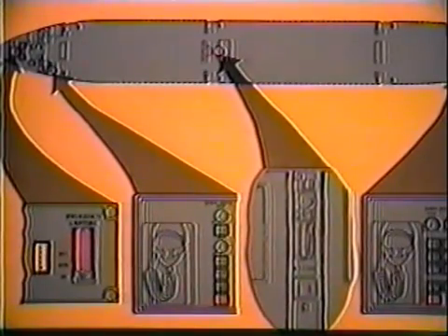There are 2 cabin switches and 1 lower galley switch that can activate the emergency light system. One switch is located on each cabin lighting panel near doors L1 and L4. The lower galley switch is located in the galley between the lifts. Once activated by a cabin or galley switch, the system can only be reset by the flight station switch.